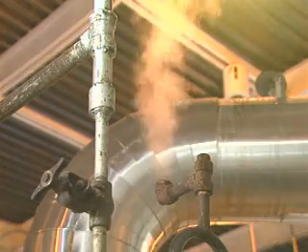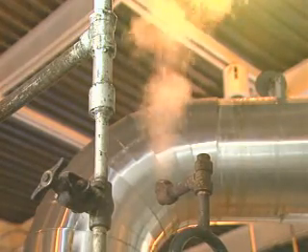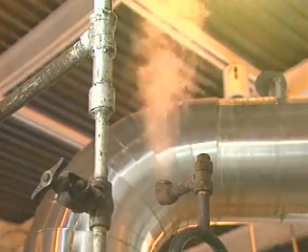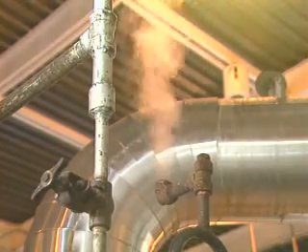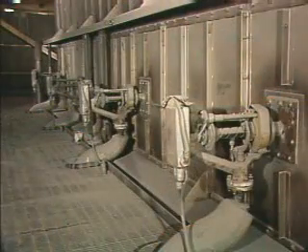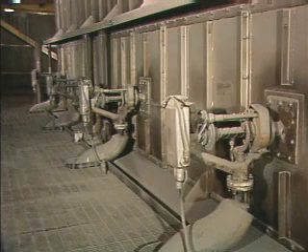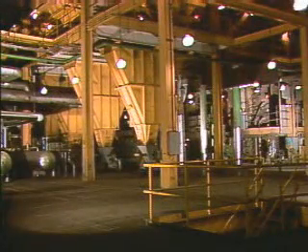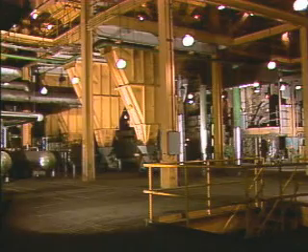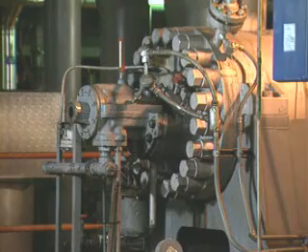Proper boiler operation requires the flow of feed water into the boiler to equal the flow of steam leaving the boiler. If too much feed water flows into the boiler, moisture could eventually build up and carry over into the main steam system. On the other hand, if there's not enough feed water flow to meet the demands of the boiler, it could boil dry. Feed water flow can be controlled in various ways.